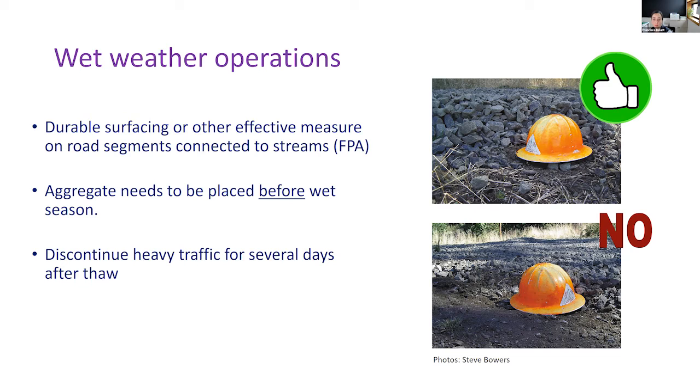If ice or snow happens, for the most part, the rule, it's not a rule, but a rule of thumb, is that heavy traffic should be discontinued after thawing, because what happens is that the top layer of the road thaws, but the bottom, or further down in the road deeper, is still frozen. So the water that melts on the top creates this mushy road, and that's what is called pumping that happens on these roads. So it's better to wait out until the thaw happens completely.